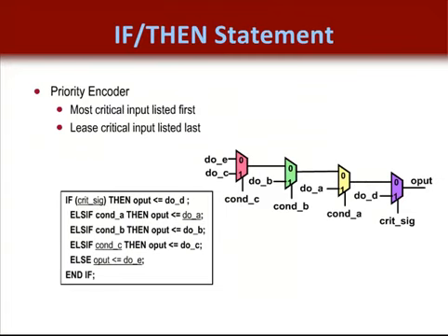So this example shows you that the if-then statement construction of a mux builds LUTs in series. It is very important that you understand that having these LUTs in series produces long delay paths. Just look at the do_e input. Its path to the output requires 4 LUTs and 3 net delays to be traveled before the output would be accurate. So this and the do_c paths are the longest and will be the most timing critical paths through this component.